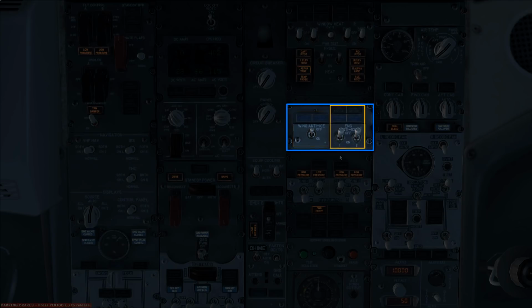Next to that, you have the engine anti-ice system, which also uses hot bleed air from the engine. This feeds hot air into the engine cowl, the front rim of the engine around the main fan at the front of the engine. Again, you have a simple on-off switch, one for each engine, and blue lights indicating bleed air valve movement and position. There are also two orange cowl anti-ice lights, which will indicate if there is a problem with the system.